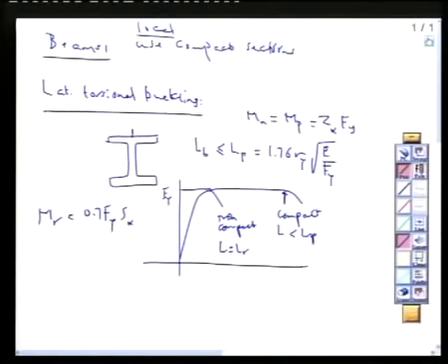Notice here we have two losses. One loss concerning, instead of approaching Fy, we are approaching only what? 0.7 Fy. If it is going to go into compact and L is less than Lp, then residual stresses start to distribute themselves from compression to tension until they are all under Fy. Because residual stresses, in parts they are tension, and in parts they are what?